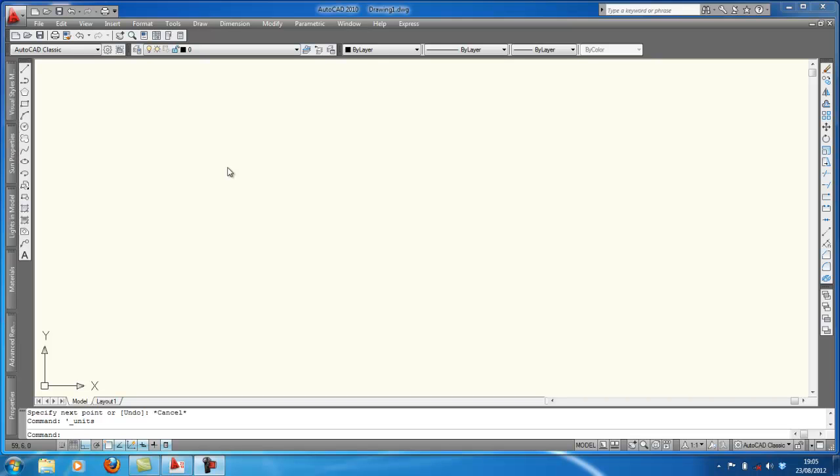Tutorial number 2, we are going to draw a house which is 9 by 9 meters and it's L-shaped. So first of all, let's define our parameters. I'm going to go to a line command and select a straightforward line. Working down here close to UCS, I'm moving the line upwards. I will type 9,000, which is 9 meters in millimeters, and hit enter and enter again, or right click and